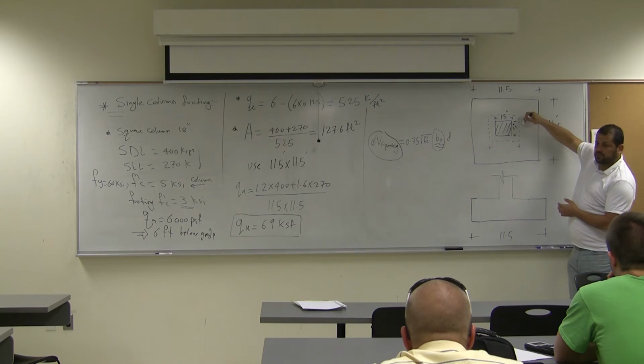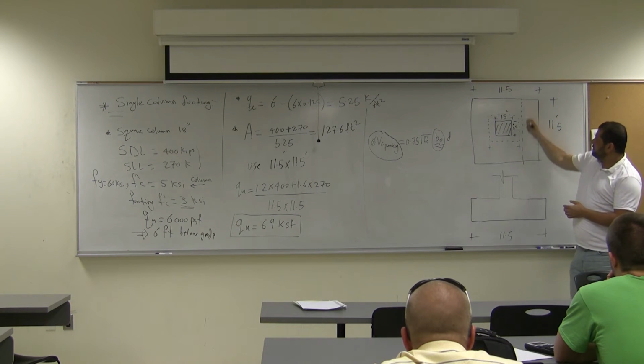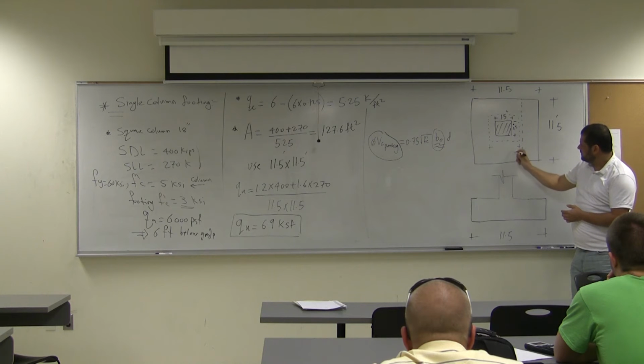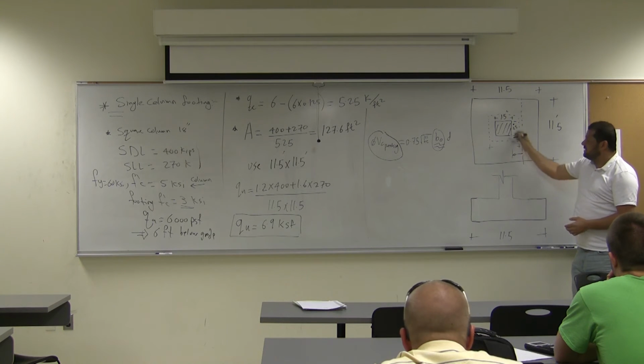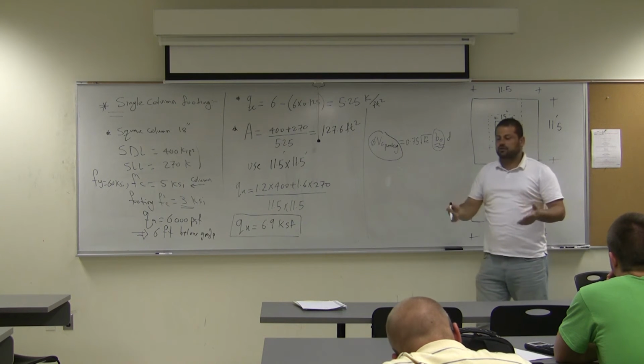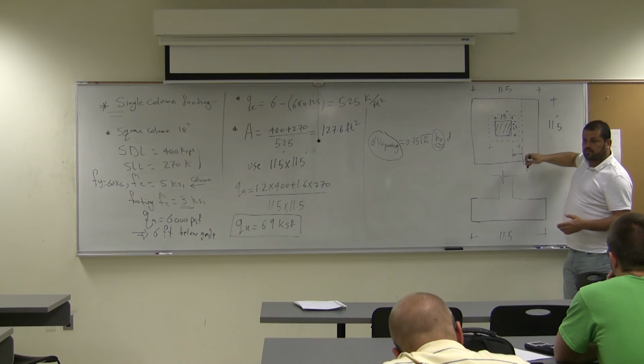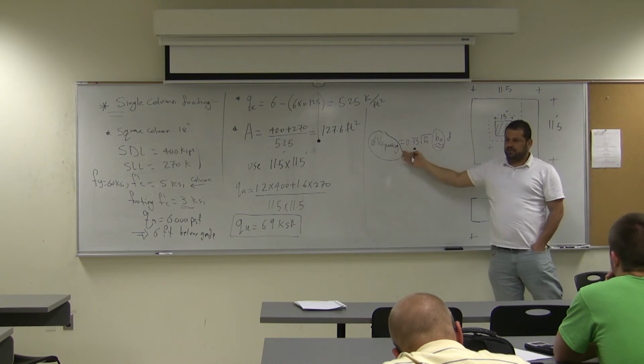This is d over 2, we said, right? That shear occurs at this one here, d from the face of the support. That's like the beam shear. It's called the one-way shear or beam shear. So here, again, what controls this here?